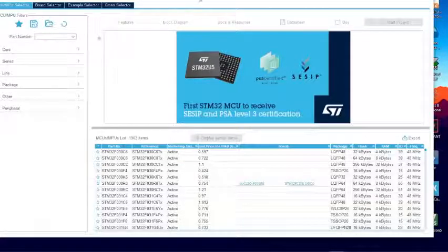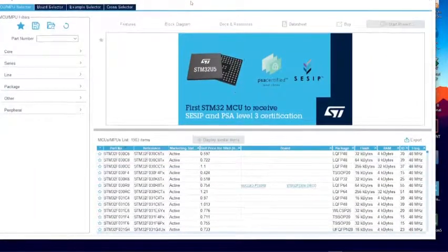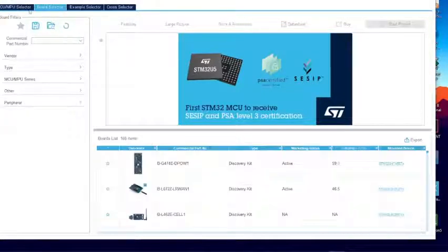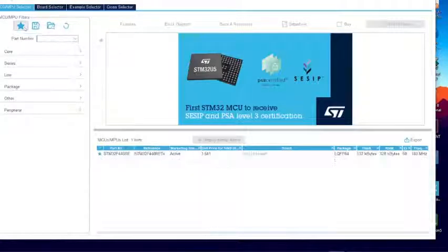Launch your STM32CubeMX, then hit New Project. You might be using a different STM32 chipset. In my case, I'm using the STM32F446RE, so you could choose that one. You might use the board selection, but I prefer the MCU selection so that I can really configure the pins and all. So go ahead and search for your STM32 chipset. I just bookmarked my chipset, and click on Start Project.